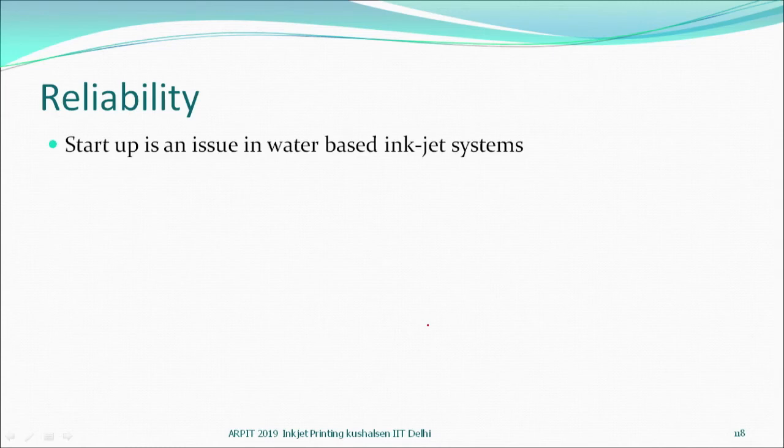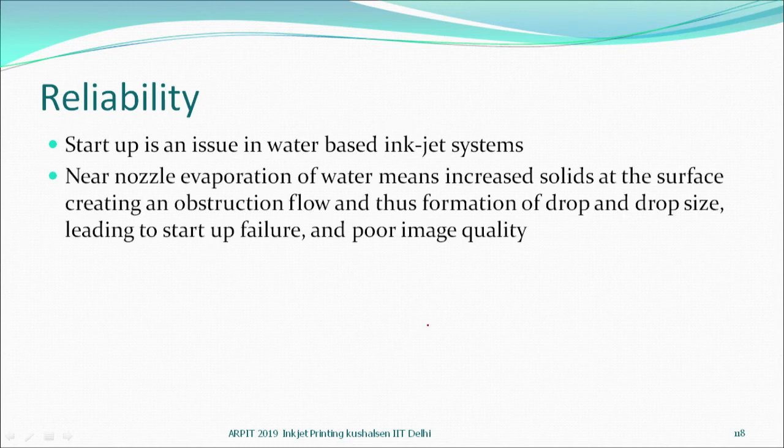Reliability, of course, at startup, if there is an issue, sometimes with water based inks, near nozzle evaporation means there is a deposit of solid, which will cause obstruction to the flow and change the drop volume and drop size. Poor image quality can result.